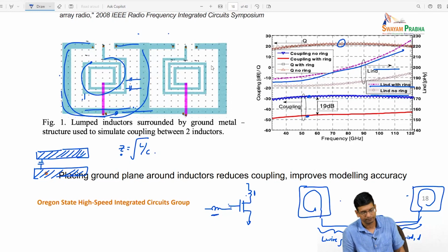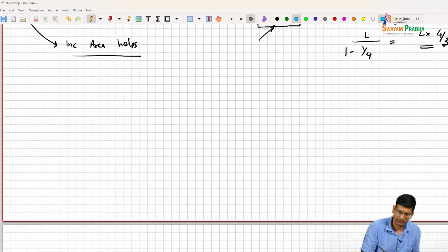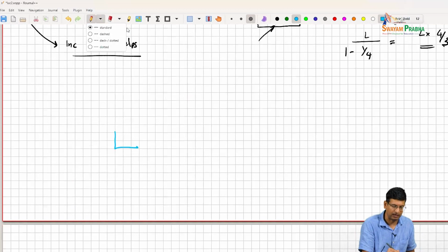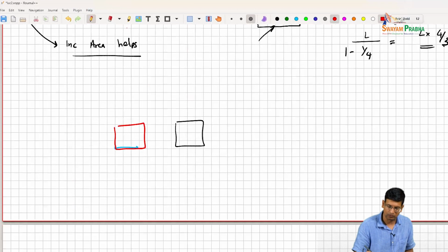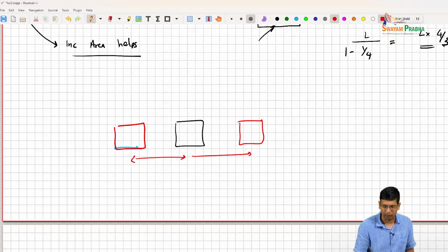the design. The general approach, yeah, I mean, is that you just have to put that exact structure that you have in the simulator. There isn't any magic there, right? I'll draw the signal and the ground over here, right? This is the pad, and if your pads are far apart for packaging reasons, right, what you end up doing actually is that you bring your ground plane quite close to your pad, right?